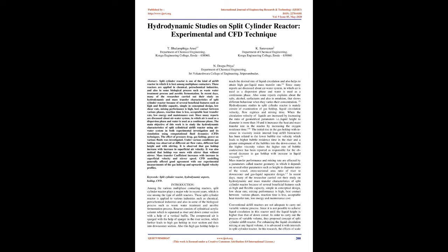The main objective of this work is to study the hydrodynamic characteristics of a split-cylindrical airlift reactor using an air-water system, in both experimental investigation and its simulation using computational fluid dynamics, CFD, techniques. The effect of pressure drop and gas holdup on various fluids was investigated. Under various conditions, gas holdup was observed at different airflow rates, different bed heights and with stirring.